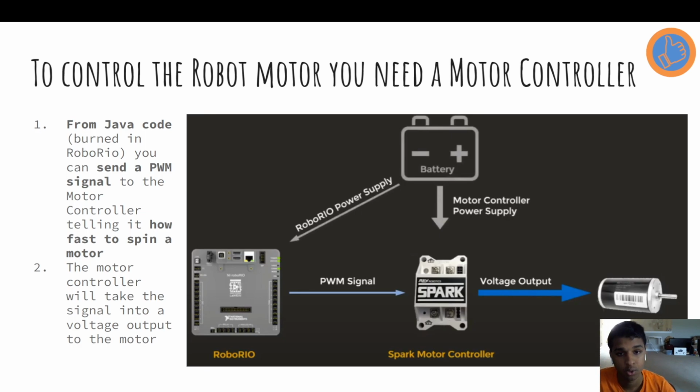Or actually, it would, because it's 5 volts. Let's say you have a 2.5 volt LED, right? You want to send 2.5 volts to this LED. Now, you might think that when you say send 2.5 volts, it'll just send 2.5 volts constantly. But what actually happens is, for a certain amount of time, it'll send 0 volts, and then for another amount of time, it'll send 5 volts. And over a period of time, the average of that will be 2.5 volts, right?